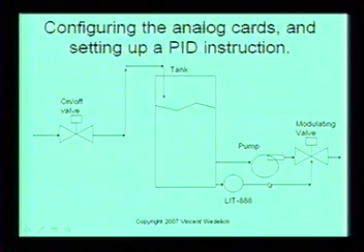But you'll see a lot of process engineers, they just kind of dot over here and point to the modulating valve, and that tells the PLC programmer, hey, these guys want me to modulate that valve based off tank level. If they had a flow transmitter here, an FIT, and they pointed this to that modulating valve, then that would tell the operator or the PLC programmer, hey, they want me to control the flow with that modulating valve, which is entirely possible. I don't know why you'd put it on the suction side of a pump. That wouldn't be a good idea. You'd want to put it on the outlet side, but neither here nor there. You could have it even here if you wanted, I guess.